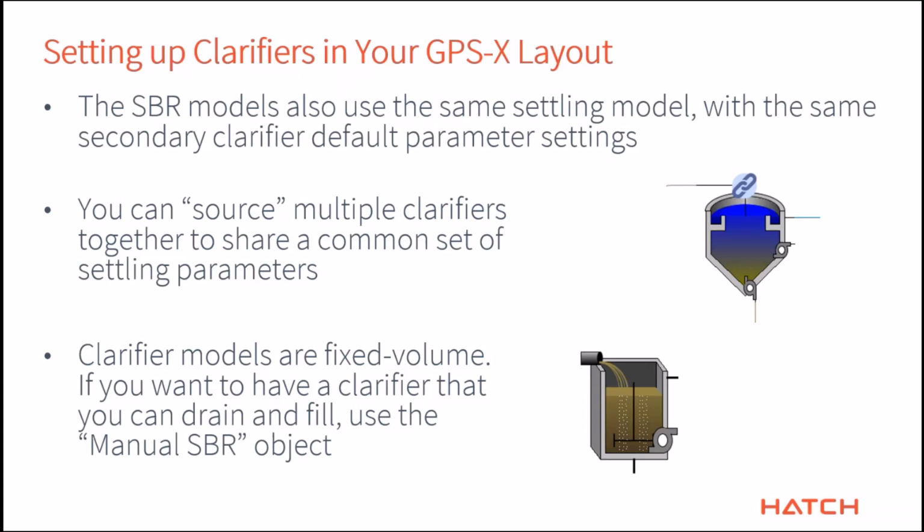Okay, so a few final thoughts on setting this up. The SBR models, sequencing batch reactor models, also use this same settling model, with the same secondary clarifier default parameter setting. So if you are using an SBR, in addition to all of the other sequencing, aeration and mixing, there's a settling phase. And so you also get settling parameters that you can use. It's the exact same approach that I've just described to you.